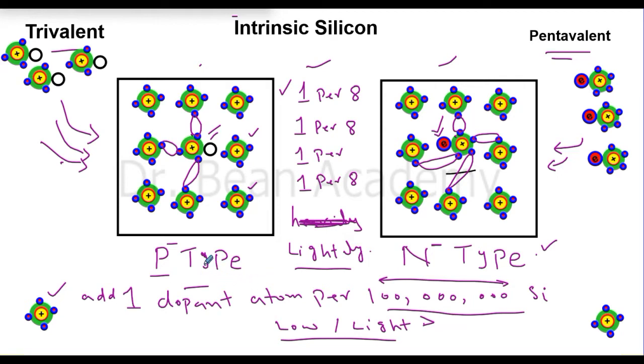If you are reading literature about semiconductors and specifically about doping, and you see a negative sign with P and N, it means it is lightly doped. What does that mean? That there is one dopant atom per 100 million silicon or whatever material is used, and once again this value is a rough value, so there may be some deviation.